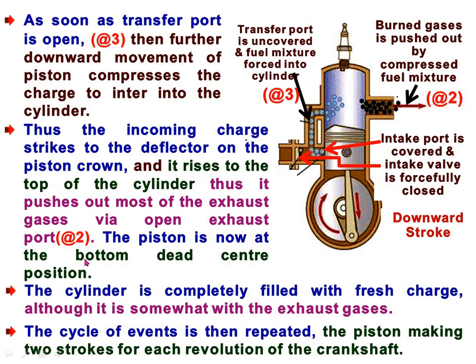The piston is now at the bottom dead center position, meaning the piston has completely reached bottom dead center, and at that time it covers the inlet port, and both the ports, transfer port as well as exhaust port, are uncovered.